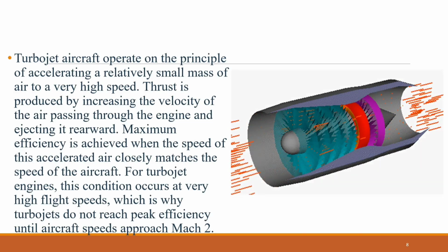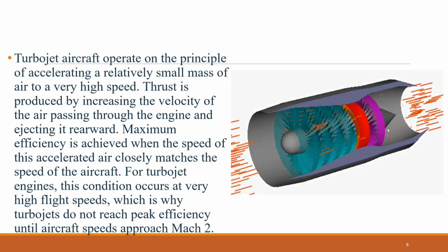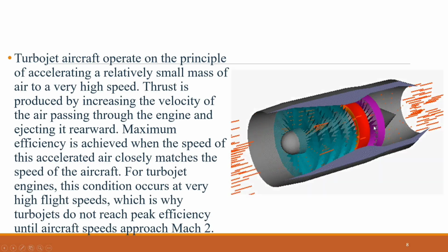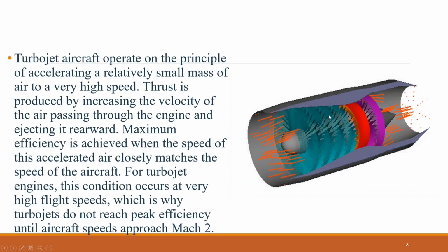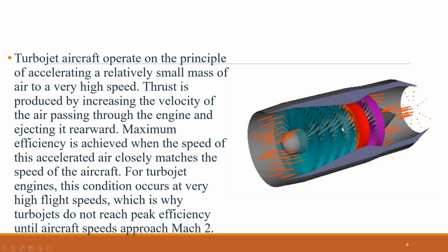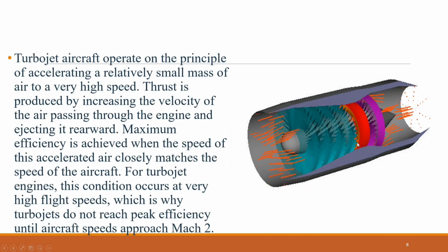Energy must be supplied to turn the compressor, and this energy comes from the turbine section of the engine. By the time the air exits the compressor, it is at a much higher pressure than the free stream air outside the engine. This high-pressure air is essential for efficient fuel burning and high engine performance.